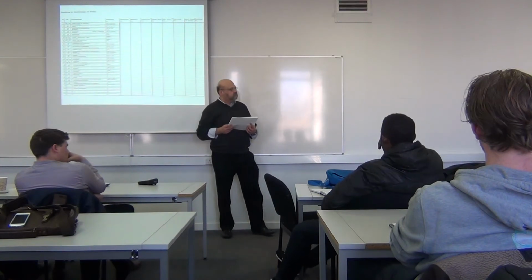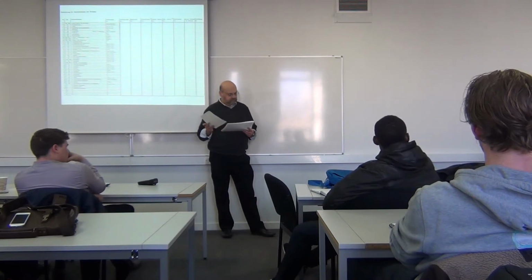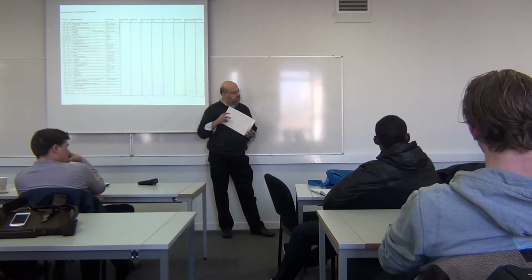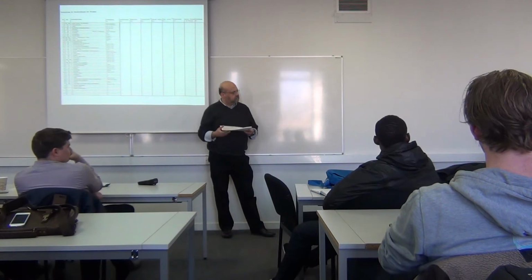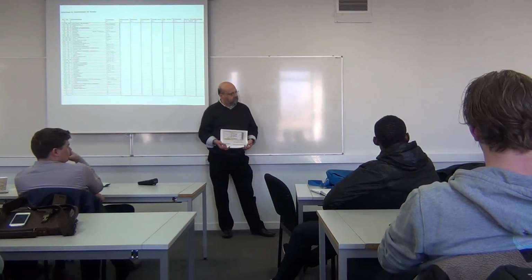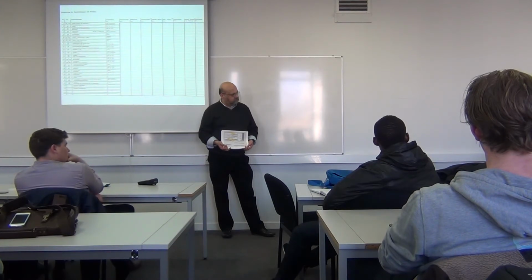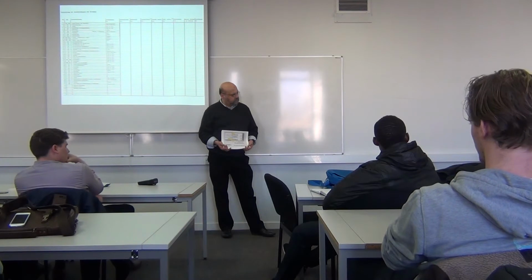And this is done after a standard in Germany or in German-speaking areas. And now what it comes to with the subcontractors is the definition stage, where you basically get your subcontractors on board, they give you the samples to reach the desired quality, or you have the lead times. If you have, for example, elevators, stairs, something like this, you have a long lead time. So this needs to be booked quite sharpish, but they don't come on site till maybe 6 or 7 months down the line. Does that make sense?